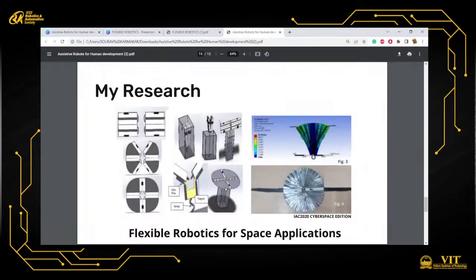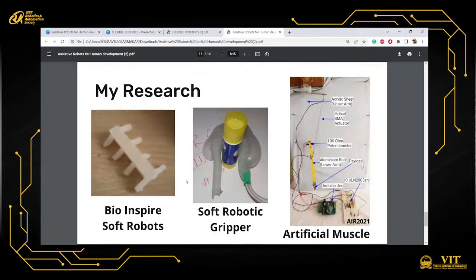So one way is, once you are done with the shape memory alloy mechanism, first you put the memory, what kind of shape you require and the final shape, then you connect the wires on both sides, and then you start the power supply. Even heat, with hot water, warm water, and also direct fire from a gas lighter or maybe a candle, can work, but it's not distributed equally. So you need to make the heat distribution equal, and then it can bend.